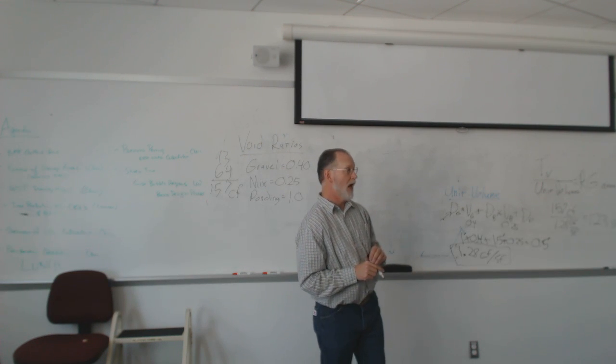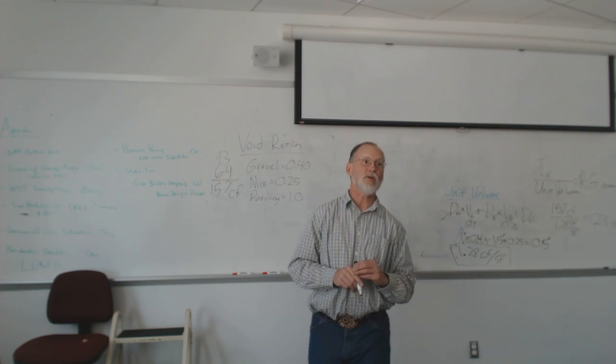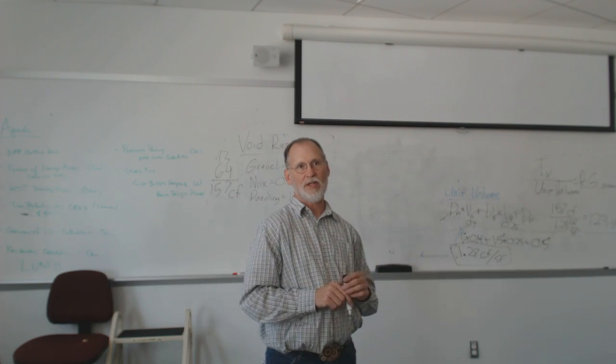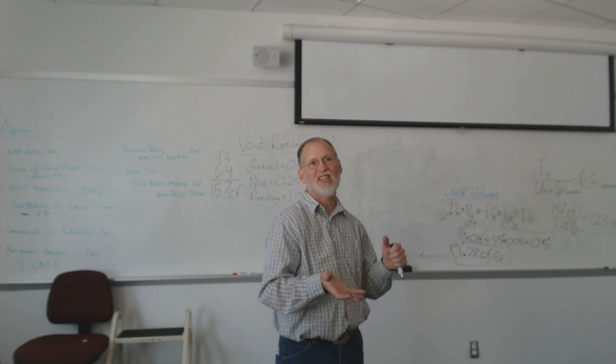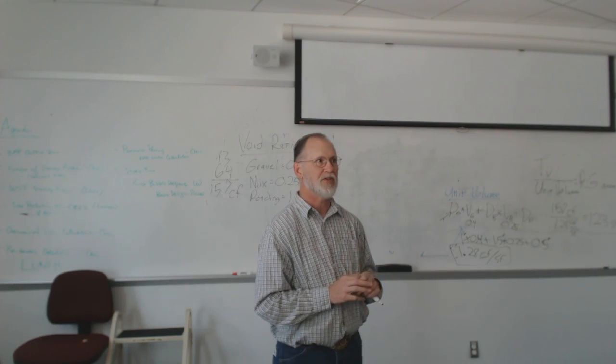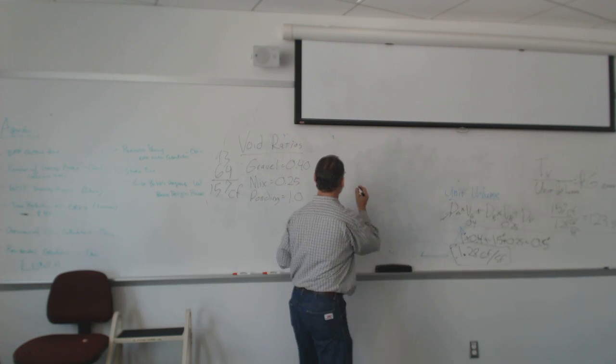So the gravel, how much would that typically go for? Usually, I don't put in anything less than about 12 inches. There might be specs where you might be able to get by with 6 inches or so on a small system. I usually put 12. But let's try a different mix.